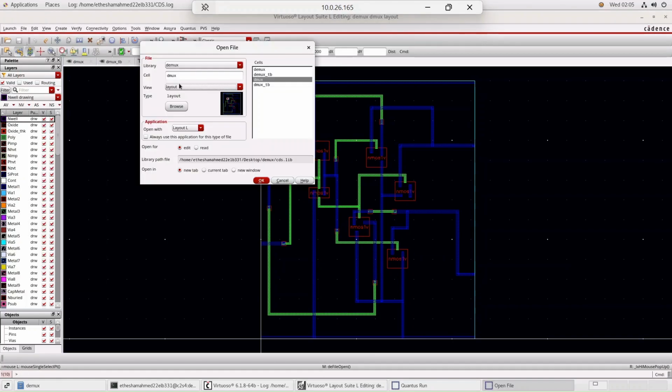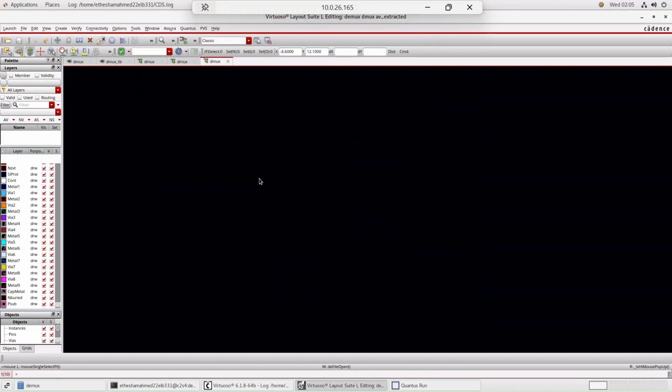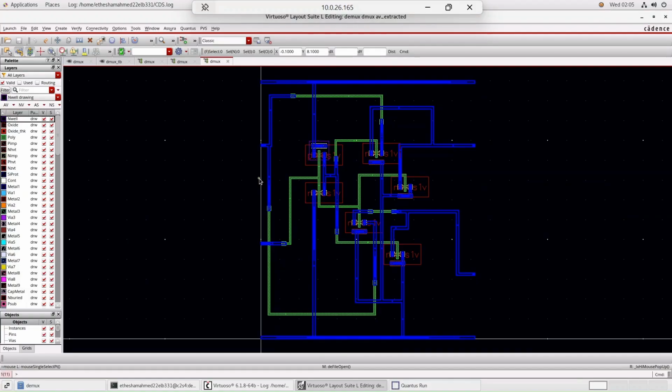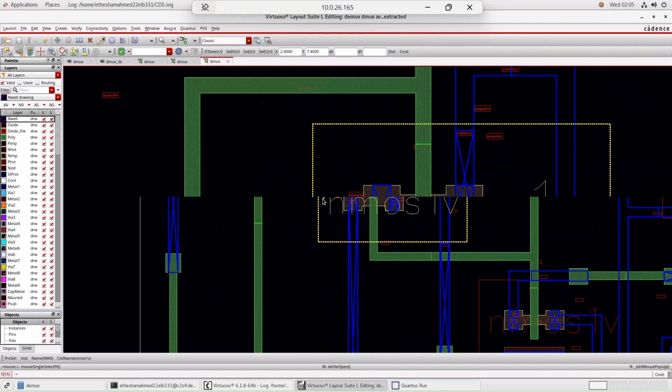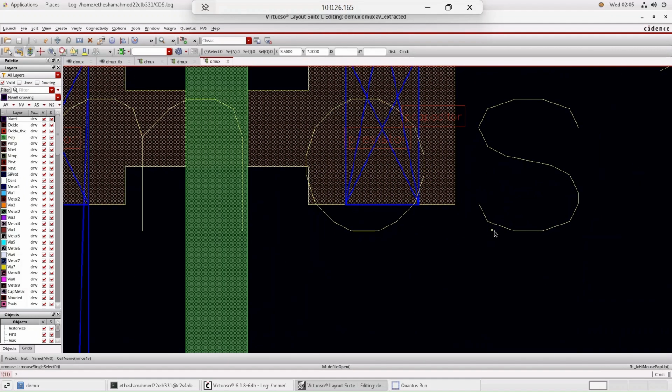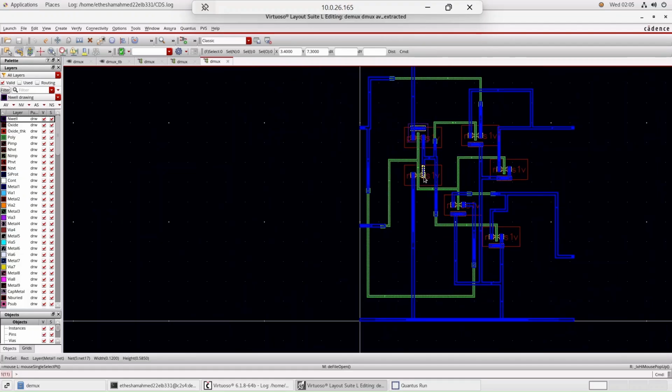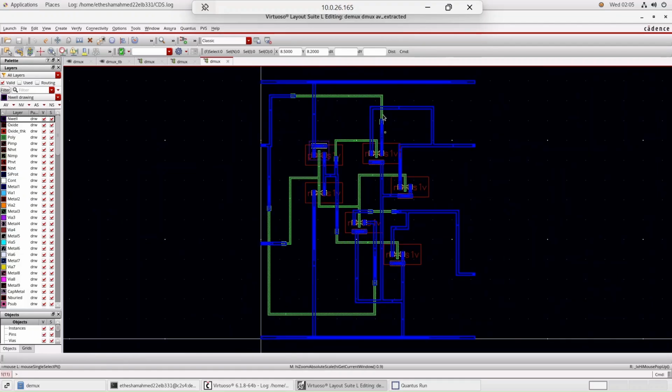Here you can see the original circuit with all the parasitic elements added. This extracted netlist represents the actual circuit behavior that will exist in silicon. The difference between the ideal and extracted view shows why post-layout verification is crucial.